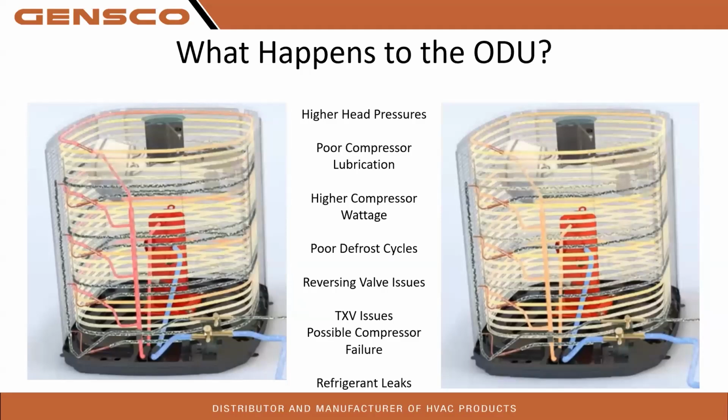And then we've got hot gas going right back into our compressor. That's even worse, right? TXV issues, yeah, the TXV can get stuck. It can get stuck wide open. It can get stuck closed. Obviously, we're going to have a compressor failure. And not as common, but it could happen.